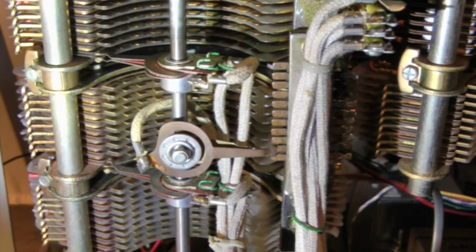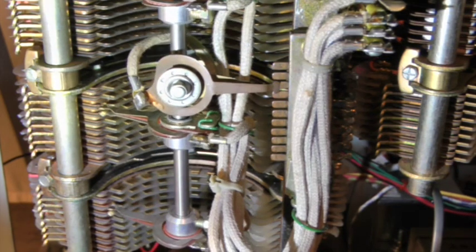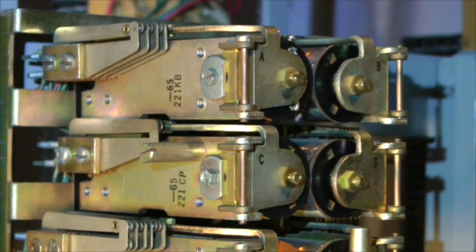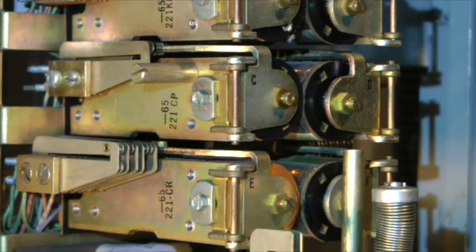When the shaft has stepped 10 vertical steps, the commutator wiper will rest on segment 0. On each call, one of the commutator segments on the line finder's bank assembly will be grounded to indicate to the line finder that this is the level on which the terminals of the calling line circuit are located. The detection of this ground stops the vertical stepping and starts the rotary stepping. That finishes our discussion of the apparatus attached to the line finder shaft.